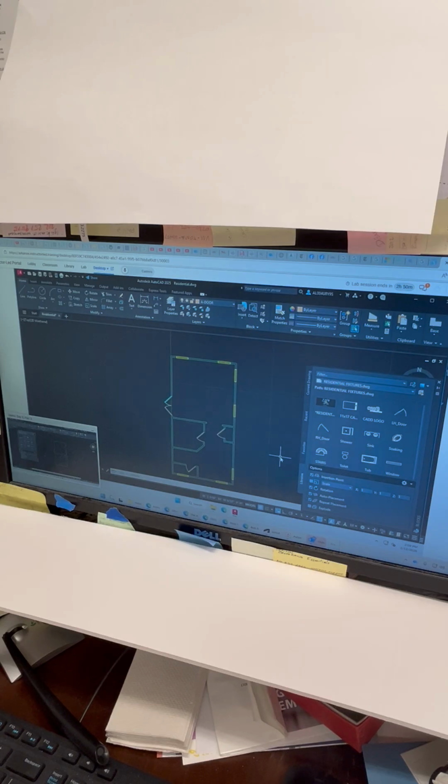All right, now let's do a couple things here. For each of these blocks, a soaking tub, a shower, a sink, a toilet, we only have one of each. So we do not need to use repeat placement. So you can turn off repeat placement. And another thing, auto placement is probably not going to work in this situation either. So you know what, you can leave it on. So just have insertion point, rotation, auto placement. That's it.